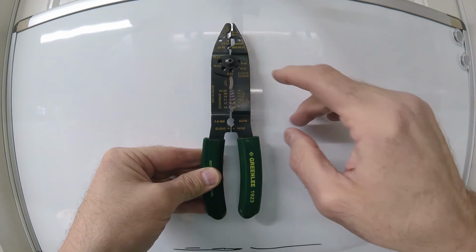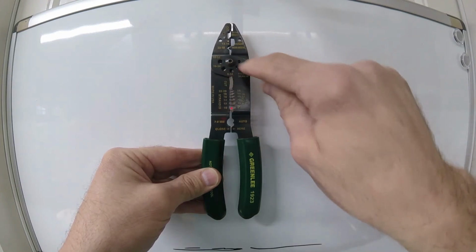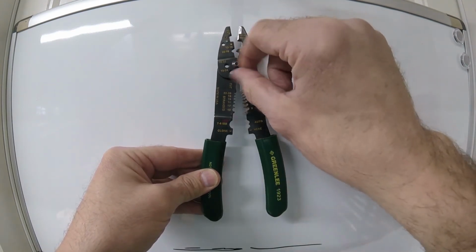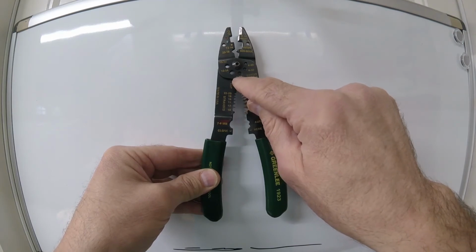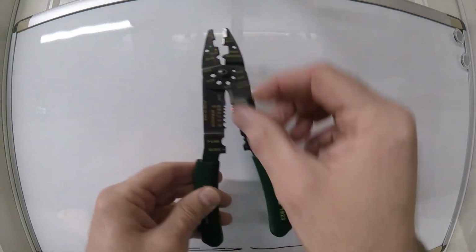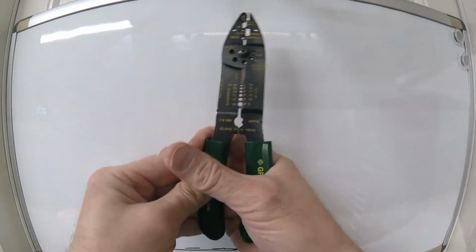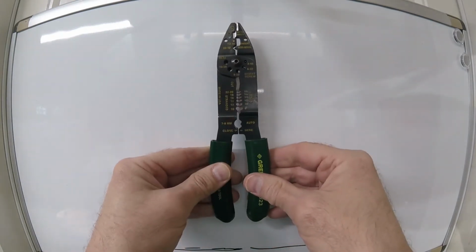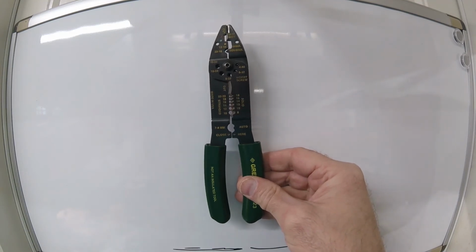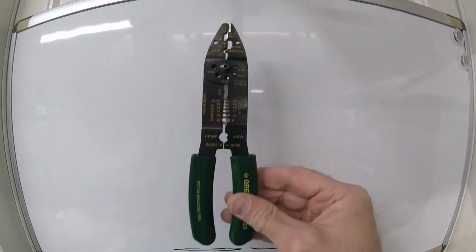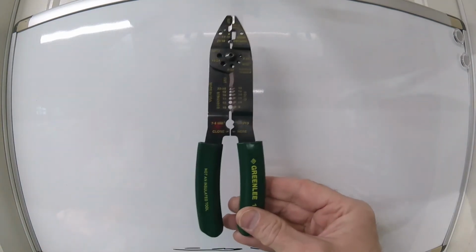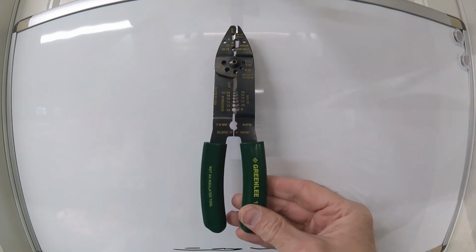And then this tool also has a place here. These holes are threaded on one side, on one of the jaws, and not on the other. And you could screw a small screw in there, like a number 8 screw with 32 threads per inch. You could screw that in there, and as it comes out the back side, you get it to the length you want, and when you close it, it'll cut that screw, and then you have a shorter screw. So sometimes you've got a screw that'll fit, but it's way too long, and instead of stacking washers or something like that, you can cut it to length. So something like this is very, very useful. It does a lot of different jobs, and if you get a good one, it does them fairly well.